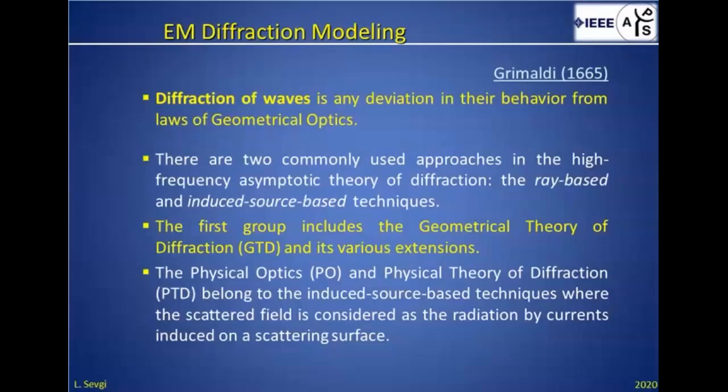There are two commonly used approaches in the high-frequency asymptotic theory of diffraction: the ray-based and induced source-based techniques. The first one, the ray-based technique, is called geometric optics and geometrical theory of diffraction, GTD. So if you use geometrical optics and rays, then you call it GTD, geometrical theory of diffraction. The second one was founded by Professor Ufimtsev, whom I mentioned in the first part.